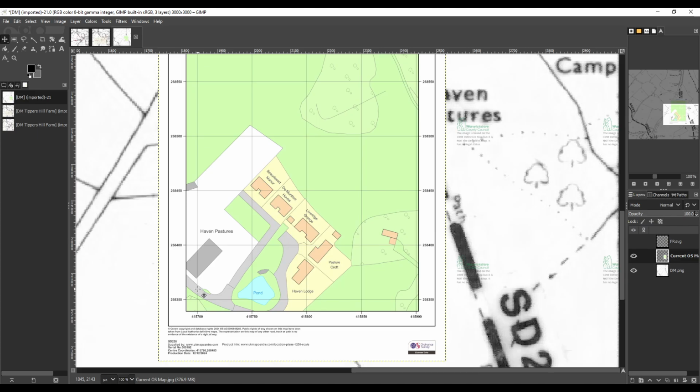the 1 kilometer square. Now we know that this definitive map and this 1 kilometer square is 3 pixels per meter. So this 700 meters times 3 is 2,100. So down in this bottom corner here, as we move the cursor about, it shows us in pixels where the cursor is. So we need to make sure that this line here is 2,100.